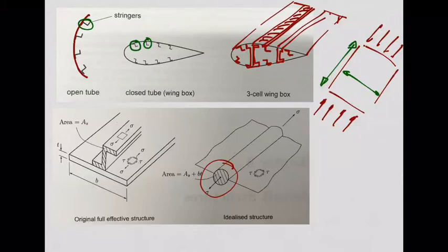So you come up with your first design, then you do this stress analysis, and then you find out, okay, the stress here is too high, the twist angle is too high, so we need to change the design. So we need to maybe put one more spar, then you need to redo the analysis again, and then you find, oh, this new spar is still not good enough, it's buckling, this part of the skin is buckling, so we need to reinforce here with a stringer, for example, and you calculate everything. So during this design process, you can calculate this many times.